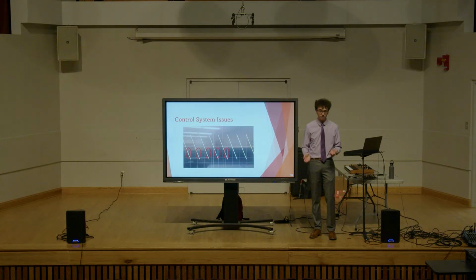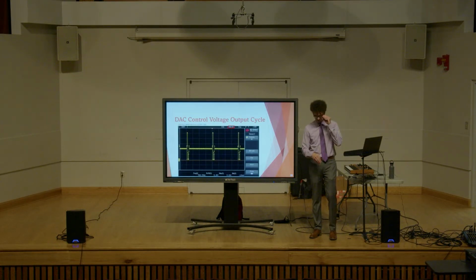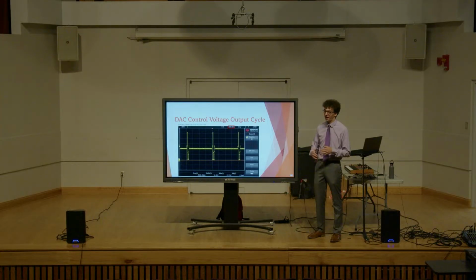And though that worked for what I wanted it to do, I also found that it put a strange loading effect on the DAC output, since it was starting to pull decent amounts of current when you wanted to discharge that held value quickly. So what I found interestingly worked was just removing that resistor and switching it to that open channel, feeding it that new voltage, and then switching it to the proper output channel. Solved the problem.